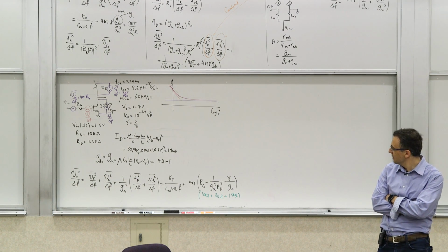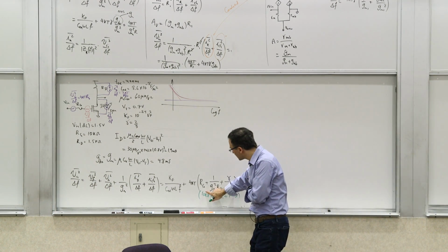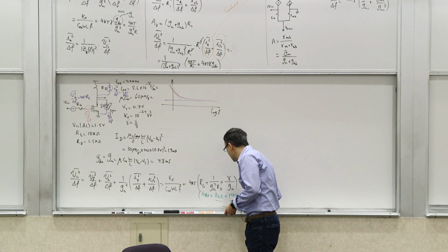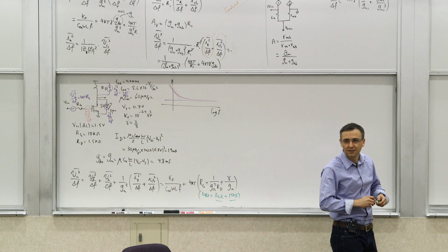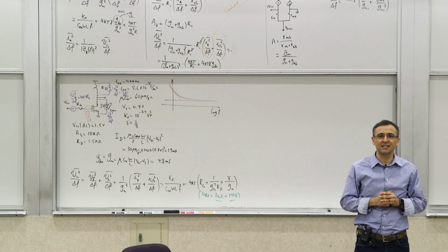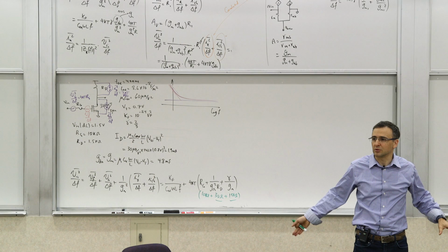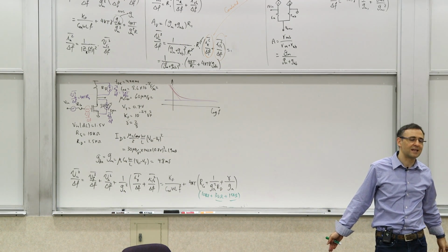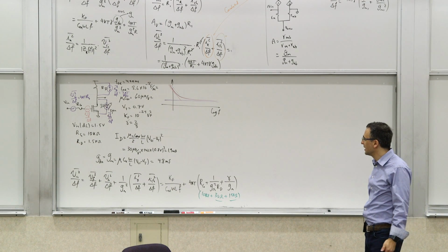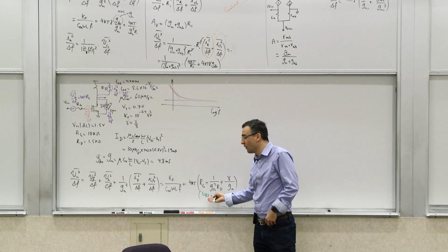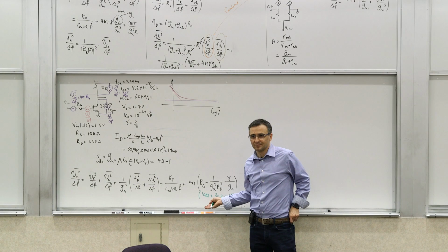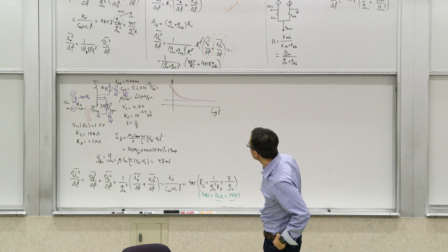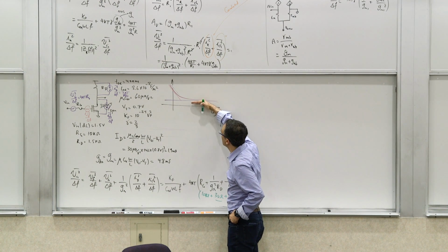The gate resistor, right? Because this guy is 10 kilo ohms, and these are on the order of 30 ohms and 150 ohms. So the gate resistance is dominating your noise, the white noise, by far, if you pick this value. It's 10 kilo. Even if you were at 1 kilo ohm, you have to be around 100 ohm for it to be comparable. Right? So if you keep these values, your noise floor here would be dominated by that.